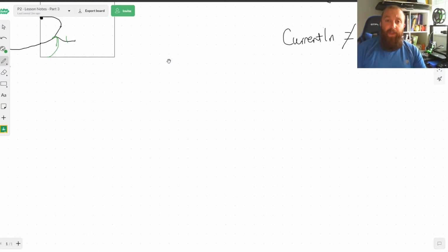The explanation was that the live potential coming in was 230 volts and the potential of the electrician was 0 volts. So if he didn't switch it off and he touched a live wire, a connection would be made from the 230 to the 0 volts. We now have a potential difference, so we get a current flowing through the electrician. That was the level of detail they wanted. So we've got this potential difference between the 230 volts and the 0 volts.